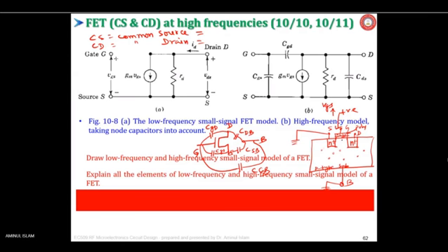Once the electrical field is strong, a layer of electrons will line up here in the channel region, under the gate silicon. This bottom layer I have shown is SiO2, silicon dioxide material. On top of that, polysilicon material, poly-Si.